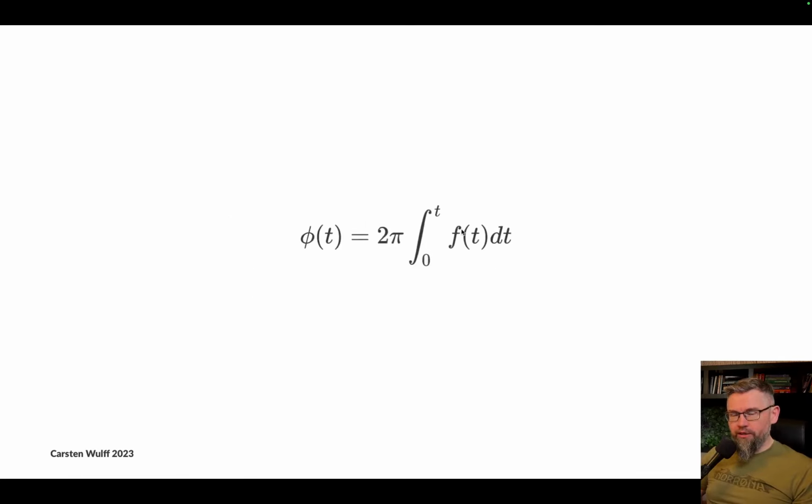Now, one thing to realize is that PLLs have clocks, which means they're sort of nonlinear systems. Voltages go up and down, and it's not a linear system in the voltage domain or time domain. However, it is possible to linearize the PLL in the phase domain. Phase is just the integral of frequency, and I guess this was back in the day of hand calculation with piece of paper. They discovered that in phase, you can actually analyze PLLs with a linear model.